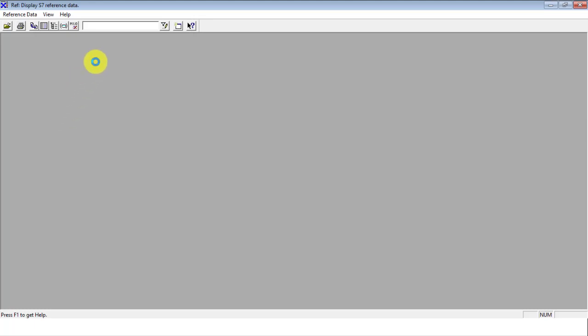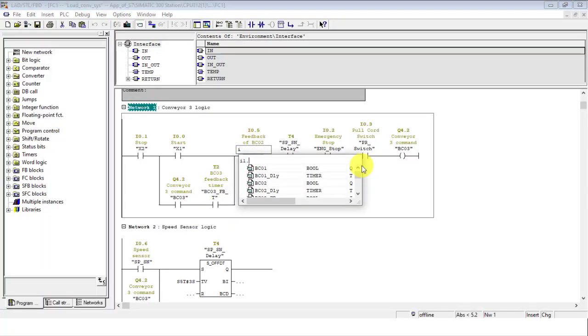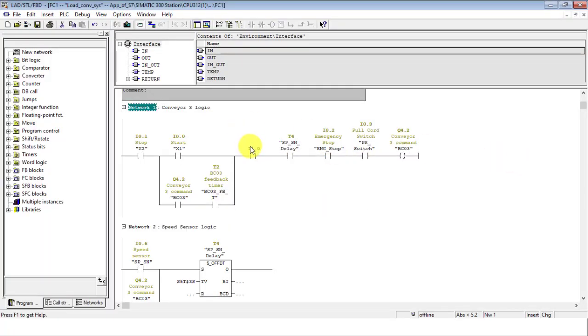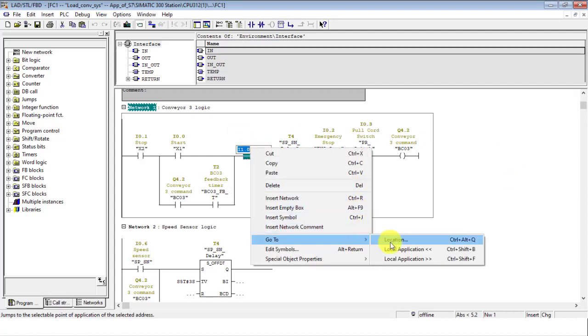You click OK, and then you can see all our timers, and also the inputs and the memories mapped right here. You can start with I1.0. I1.0 is going to be the input that is going to receive our overload signal.